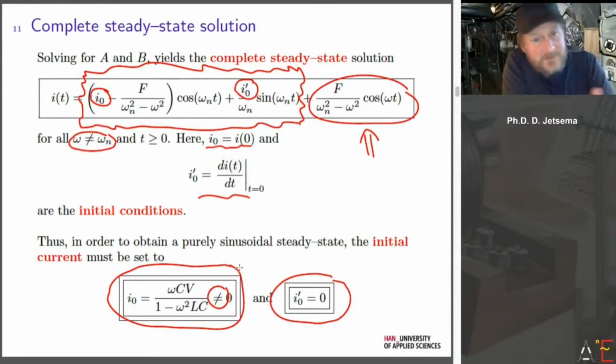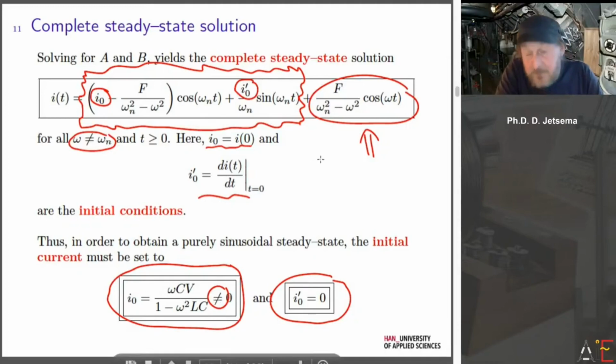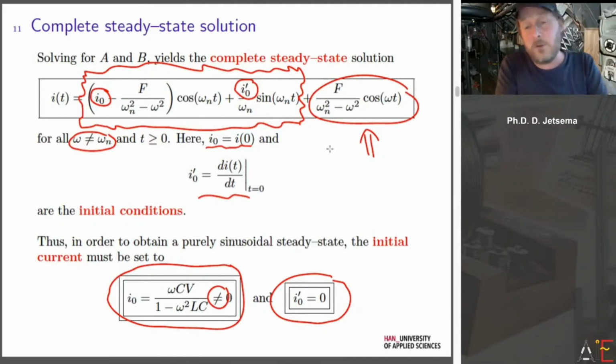When I was writing it, I was thinking that from a systems and control perspective this is obvious, and you also find these things in mechanical engineering books. But then I sent this paper to the conference, and it was actually very well received. So even though you do something almost trivial, it seems to be forgotten somehow. But this is very important. Otherwise, if you don't set this initial condition exactly like this, your phasor algebra is simply not valid. And if you implement your filter in a simulation program, you will see that it doesn't work. Actually, it perhaps makes the situation a lot worse.